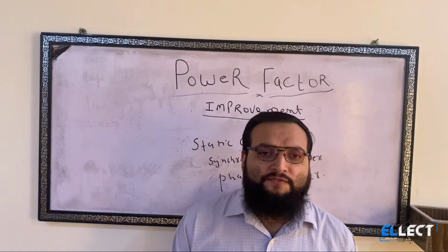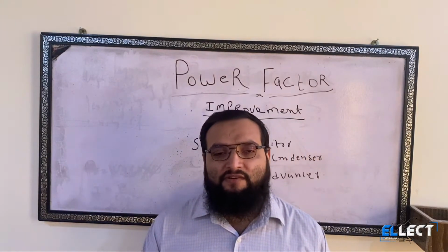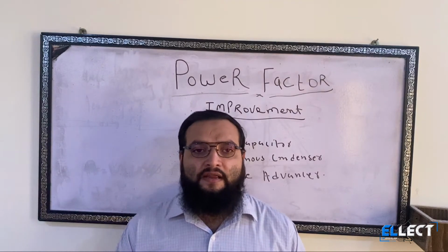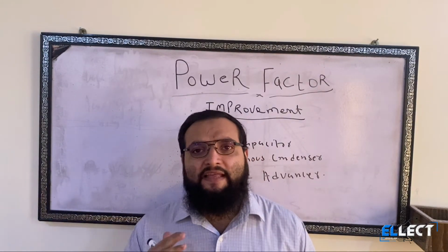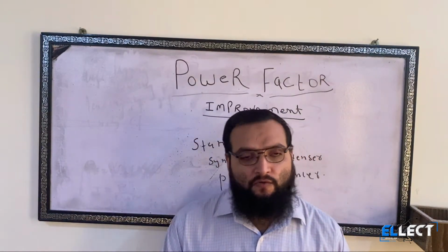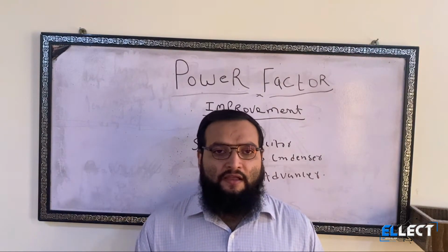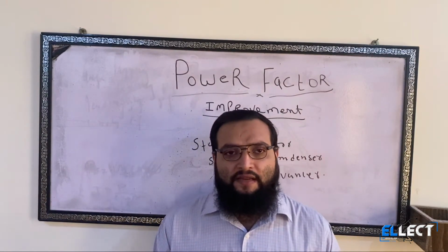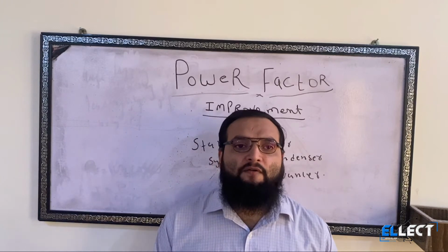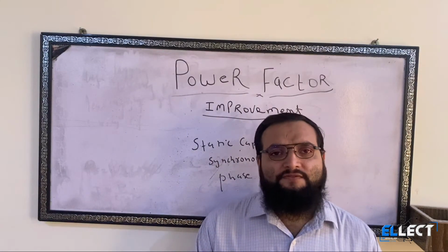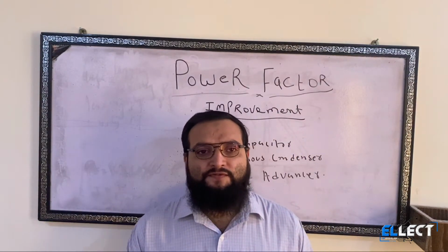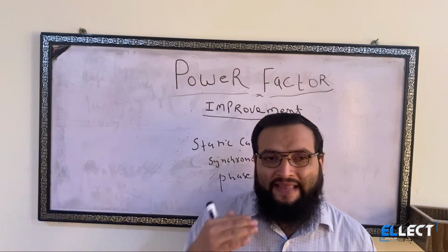As we know, most of the load connected in industries, factories as well as domestic is inductive load, which causes the lagging component of current of the load. If the lagging component of the current increases, it decreases the power factor of the load. That is why we have to do something that neutralizes that lagging component.